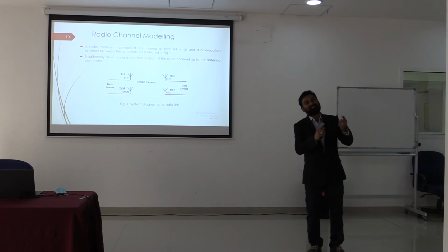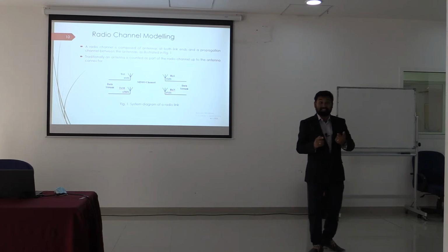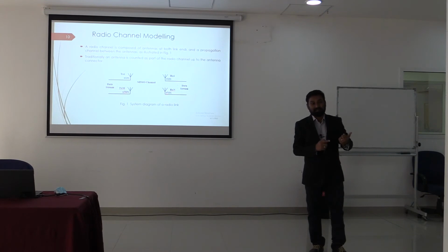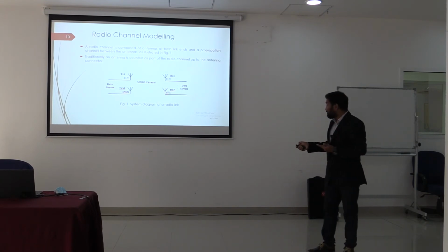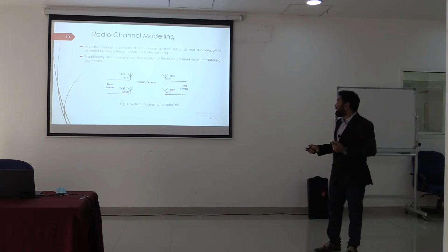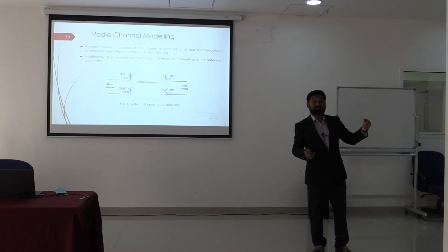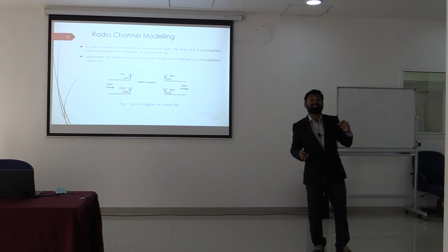So the challenge is converted into an advantage here, but the problem is how effectively you are going to create uncorrelated multipath channels. Usually multipath is a disadvantage in a communication system, but in 5G MIMO, we are taking this multipath as the advantageous one. The only challenge is how far these multipath channels are spaced. That we call spatial reuse. So the analysis of this particular channel modeling is based on space-time coding. Space plays a vital role, in how effectively you are placing the transmitting antennas with reference to 1, with reference to 2, with reference to 3, to create multipath or uncorrelated multipath.